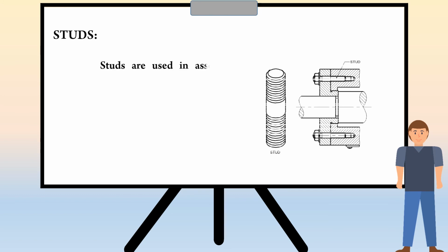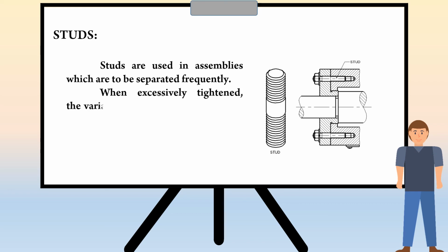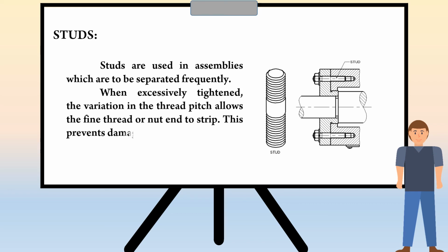Studs are used in assemblies which are to be separated frequently. When excessively tightened, the variation in the thread pitch allows the fine thread or nut end to strip. This prevents damage to the casting.